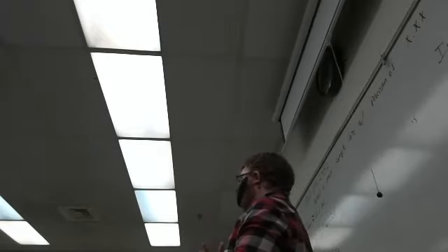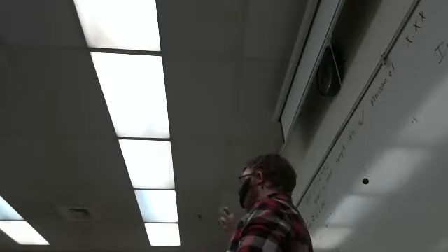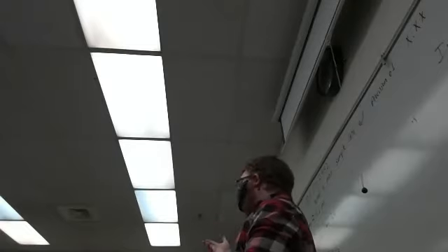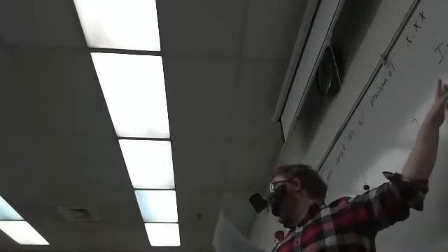I will draw this, one output. Do you need ground and power on that? No, I would not count. If you put ground and power, I would probably get confused and mark it wrong, and then you could say, oh, but I was counting ground and power, and get points back. It's not wrong, but remember, anytime we write a constraints file, we never put ground or power, because those are dedicated pins. Ground and power is not really an in or an out, it's a supply, because you could run it totally without supplying it from the FPGA.